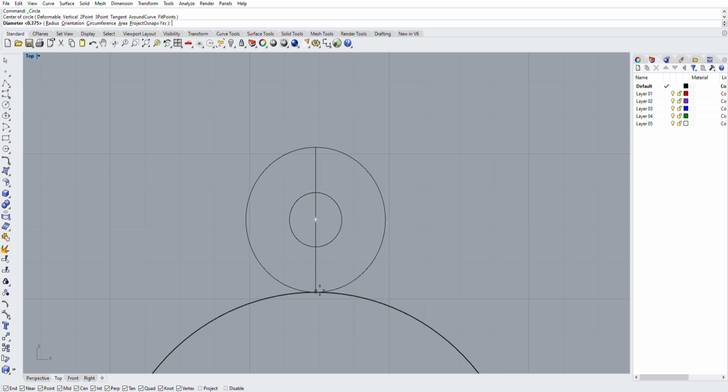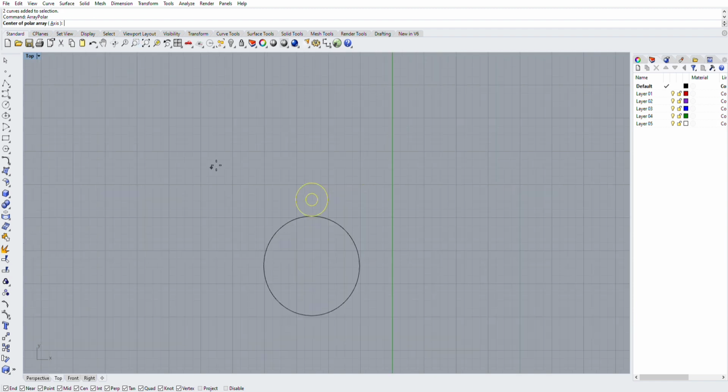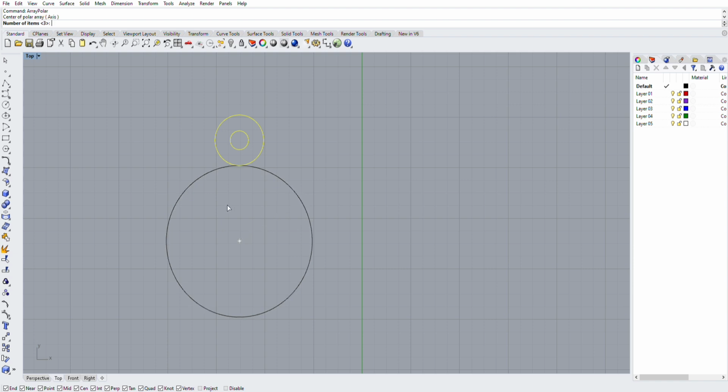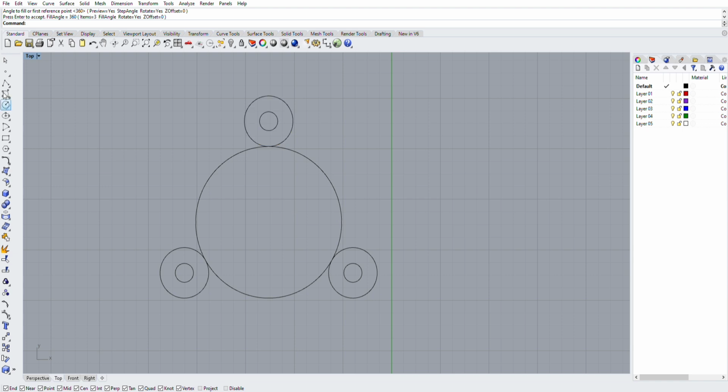So outside of that, just grabbing a circle tool, and from the center of the bolt hole, run it out to our center flange. Aesthetically, it's just something that I tend to do a lot. That 1-inch circle seems to fit pretty good. And we're going to use polar array. I use this tool so much for repeating patterns around a center point. We select 3 as our units. Our degrees are 360 degrees. You can literally click the enter key twice and it sends it around the circle.